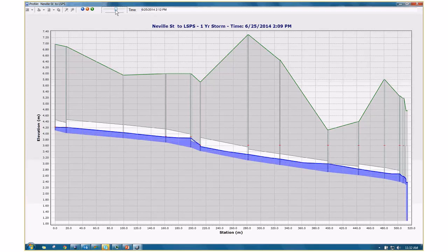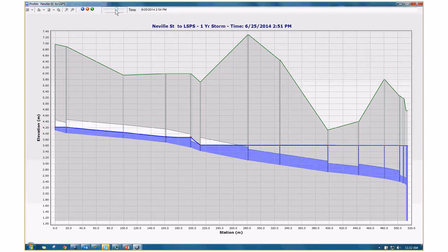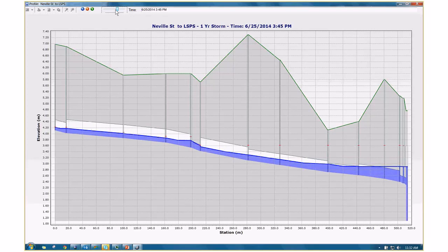So it can give us the overflow conditions as well. It will not only give you that, it will also help you understand whether the Froude number is changing drastically or not. Because as the Froude number changes drastically, it may cause a hydraulic jump in your network that may damage your pipes, right? So transition between supercritical flow to subcritical flow, and see the dynamic. It will also calculate the profile of the water level, M1, S1, S2.